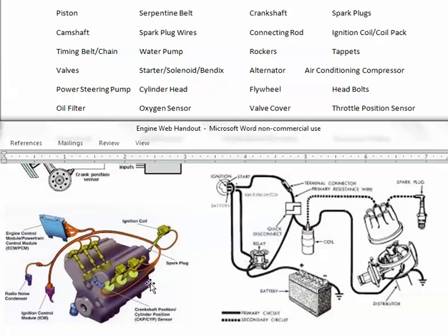If we go look at the purple one, you can see that we have an ignition control module, and you have, should be on here somewhere, your crankshaft position sensor or camshaft position sensor. So off of your camshaft, we could and should be able to link your ignition system, because that's going to pick up the location, send the information to the controller or ignition module. From the module, it will send it to the coil pack, and from the coil pack, we are going to send it to the spark plug.